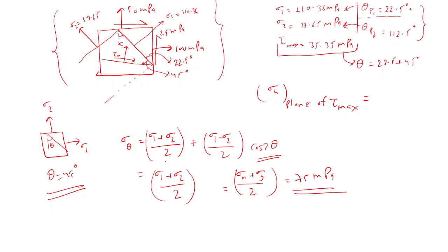So now what conclusion have you got from here? If you have been asked to find the maximum normal stress at the plane of the maximum shear stress, whatever the loading would be, you need not see, just simply add the normal terms and divide by 2, right? So this one conclusion you keep in mind. Any doubt till here? Then we go further.